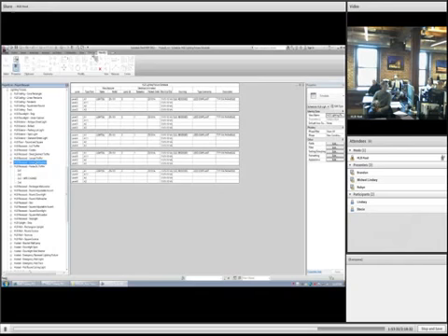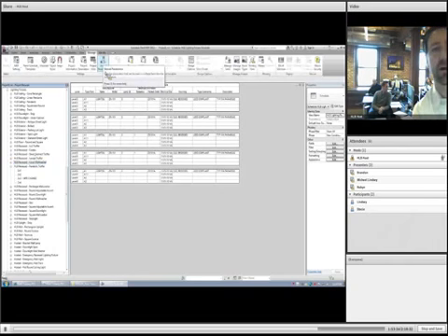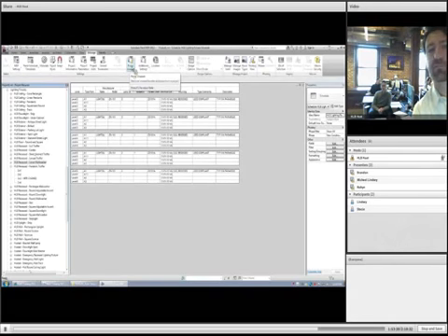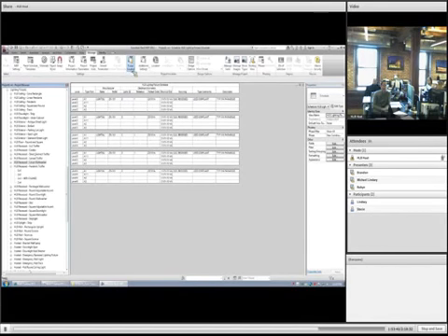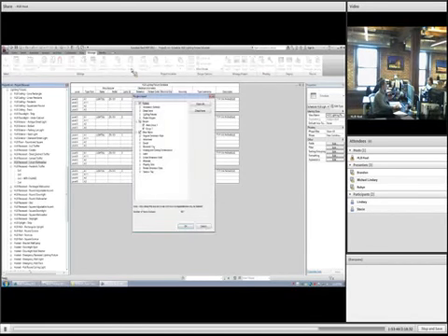Sure, you can start it, and this is actually something we should talk about from a management standpoint of your project. If you get going and you realize you don't need everything, or you just need to clean up every once in a while, off the Manage tab, there's a Purge Unused. Yeah, certainly. But you will lose anything you haven't used. So in this case, all those fixtures that we haven't used will go away.